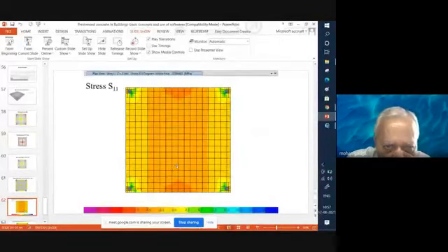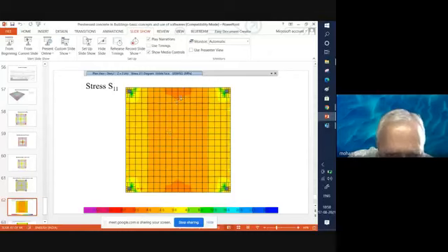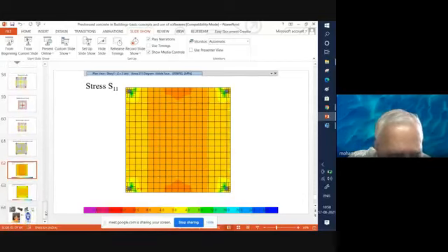Now these are the stresses which are developed in the slab. This is stress S11, which is the stress in the X direction. You can see that the entire chart has color coding. There is a stress varying from this mild red color that you see. It has a stress of about 8 to 12. That is the kind of stress that you are getting at these points. Similarly, you are getting stress near the column, which is reasonably high. Locally, of course, very high stresses are developed over here and so on.